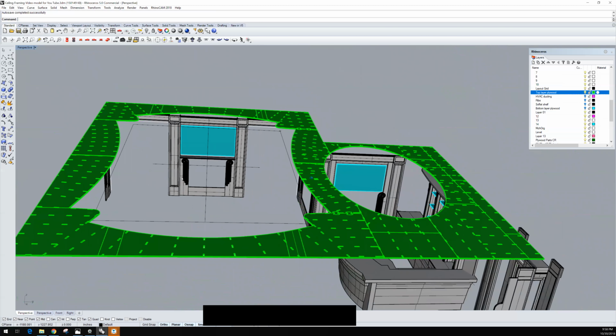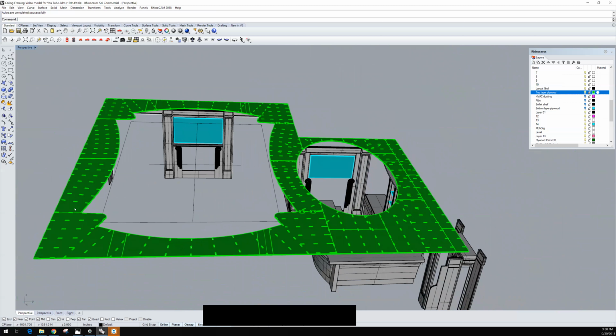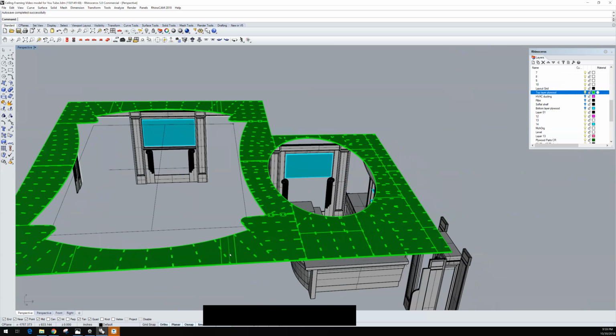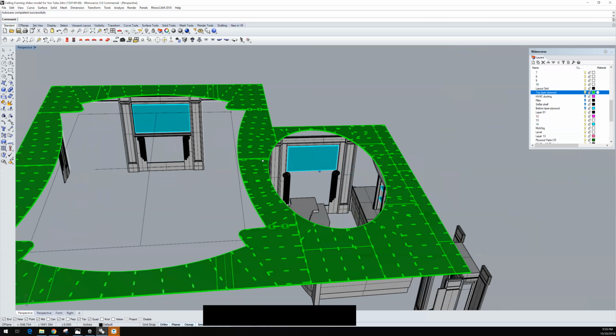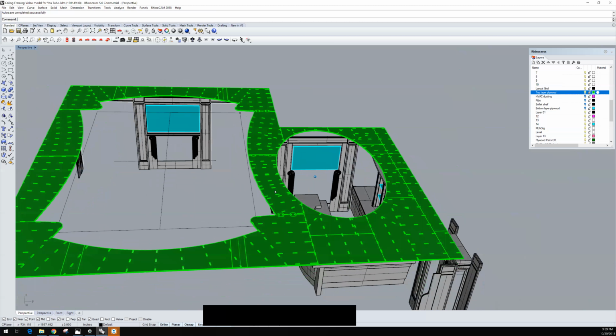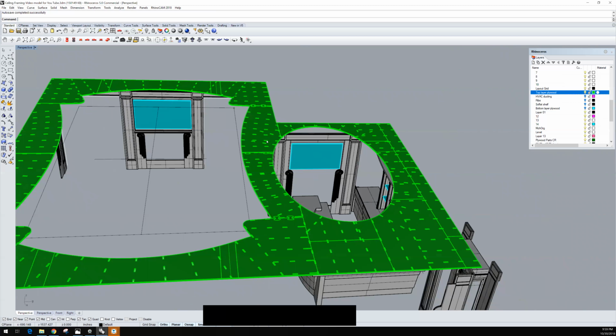And what that did is that allowed us, as we installed this green layer here and traveled around the outside, to know that we were in tight tolerance. We were staying around this middle piece here. By the time we got all the way around, and this was our last joint, we were within a 32nd of an inch, and we were able to just bring those together with a few taps on a hammer or a clamp, and then put that last set of dog bones or jigsaw puzzle pieces in there to get that fabricated. This thing was all screwed off to the framing, to the joists, so it was very, very stout.